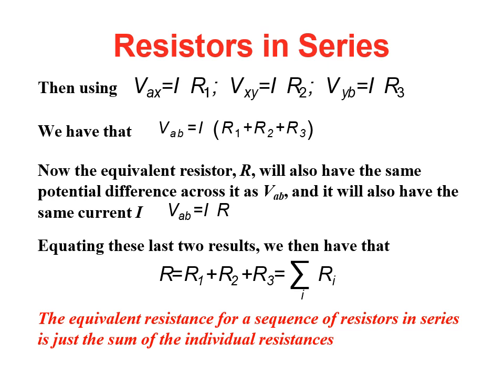Now the equivalent resistor R will also have the same potential difference across it as VAB, which is your total voltage, because R is your equivalent resistance or total resistance of the circuit. So it will also have the same current I. So VAB equals I times R.